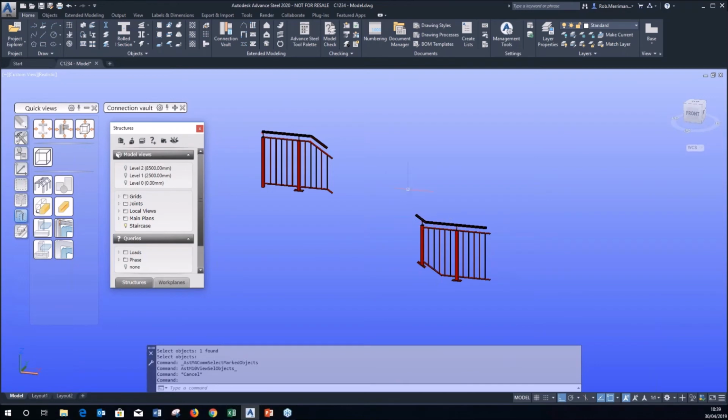And what you don't want to do is run your fabrication drawing to find that. Then you have to delete the fabrication drawing, find the error, sort it out, change the numbering, and then rerun the drawing. So again, this is something that I used to do on anything that I've manually modeled. I would check before I actually ran the drawings.